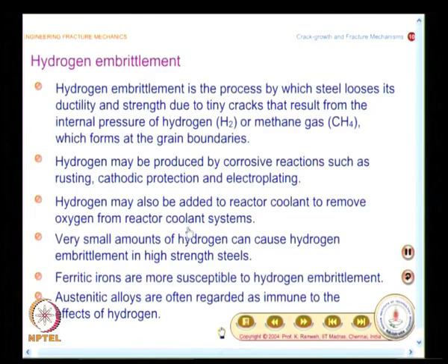In fact, an observation like this is advantageous, because if you know your corrosive environment, and there is a possibility of crack growth by active path dissolution, then use an appropriate quality of steel. On the other hand, if you are going to have predominantly hydrogen embrittlement, go for austenitic steels. So, you have a via media: by selecting an appropriate material for your structure, you are able to overcome or minimize such problems. I suppose you had time to take down the points that are listed,